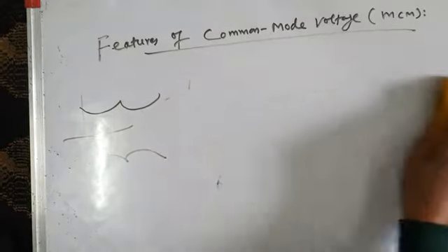So these are some of the features of common mode signal. Number 1, common mode signal must have a periodicity of 120 degrees. So therefore it will have only triplen frequencies. And another thing is that the common mode signal must have 0 average value for equal loading of all the 6 devices of inverter. So that was summary of what we have discussed in module number 3, especially in 3-phase PWM voltage source inverters, continuous PWM techniques like sine triangle modulation or third harmonic injection PWM technique, and discontinuous PWM techniques like various bus clamping PWM techniques, and features of common mode signal and all that.